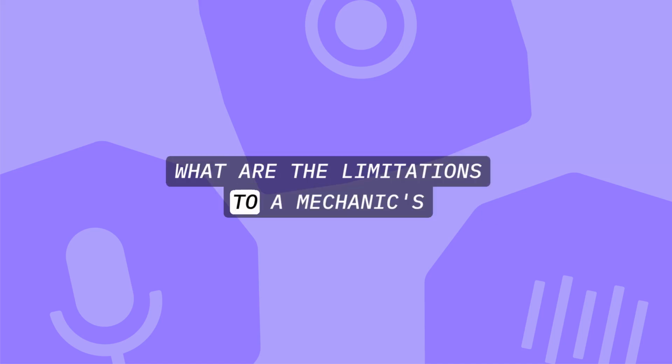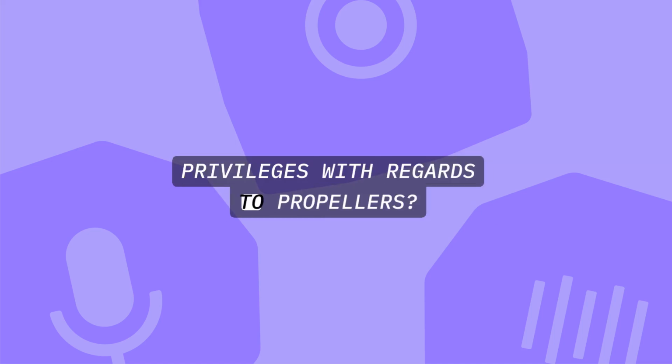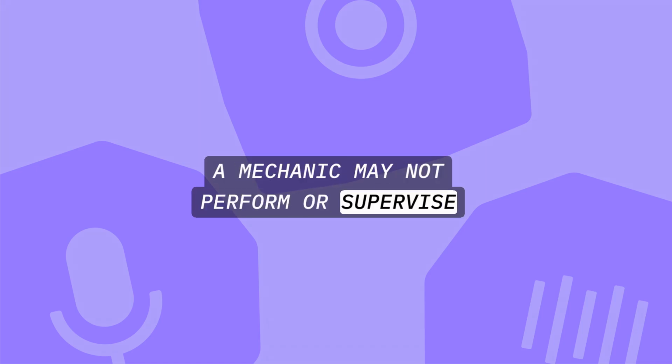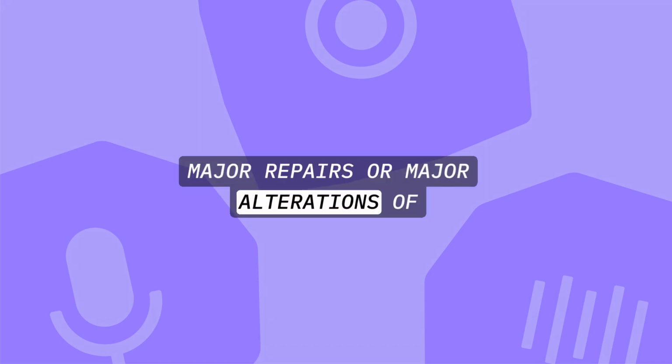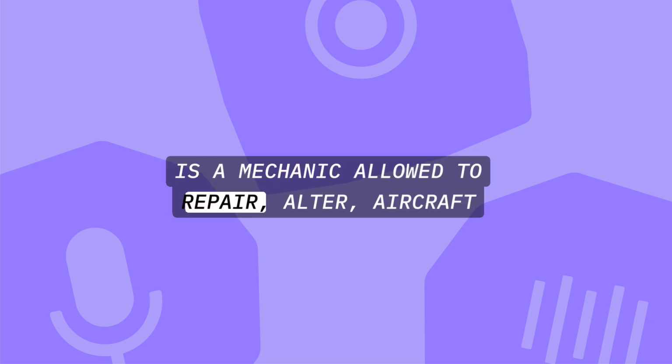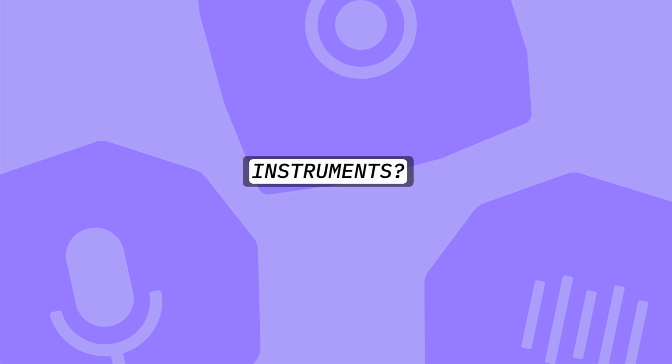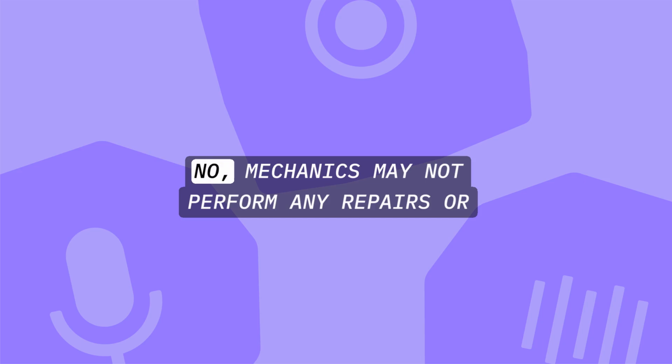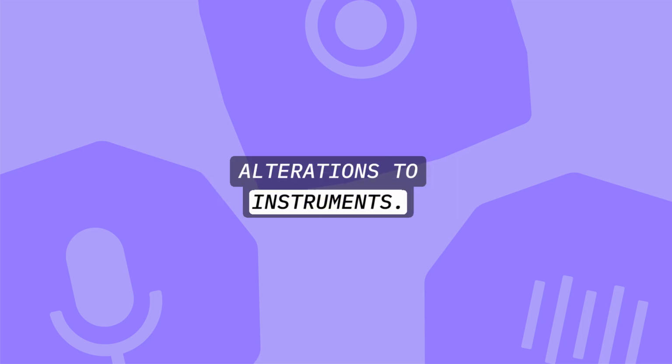What are the limitations to a mechanic's privileges with regards to propellers? A mechanic may not perform or supervise major repairs or major alterations of propellers. Is a mechanic allowed to repair or alter an aircraft instrument? No. Mechanics may not perform any repairs or alterations to instruments.